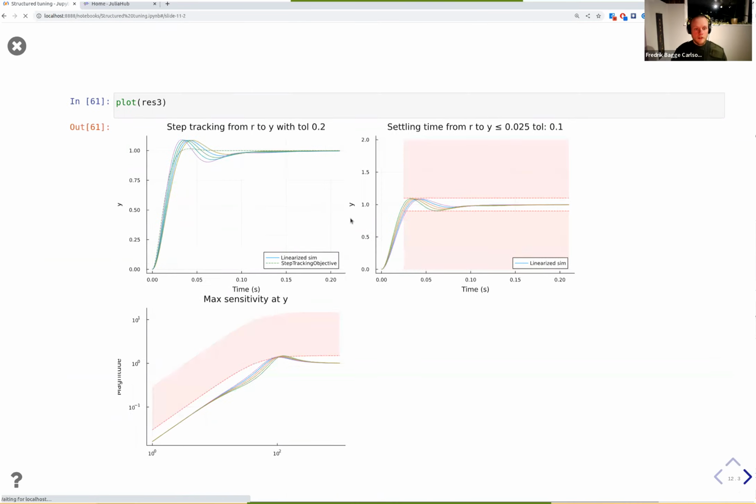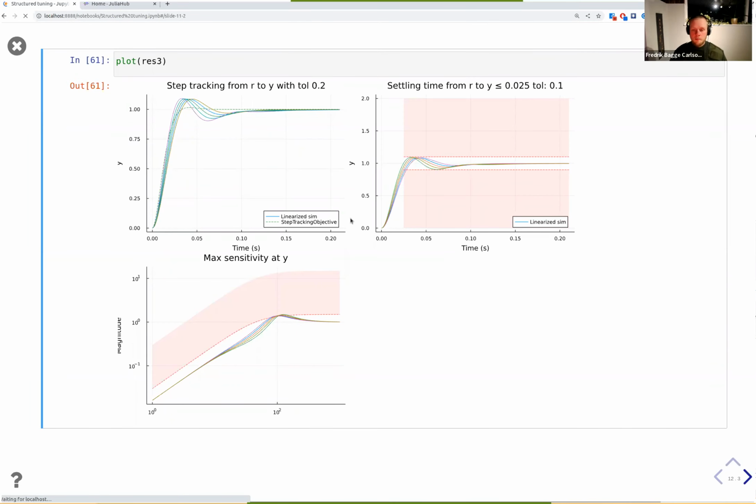So no worries there. But this is really a powerful method to be able to achieve robustness in a different way than the classical gain and phase margins. The gain and phase margins are there for us to be robust against uncertainty. But that's kind of an unstructured, diffuse kind of uncertainty. Well, the gain margin is not very diffuse. It tells you how much the gain of the system can vary.